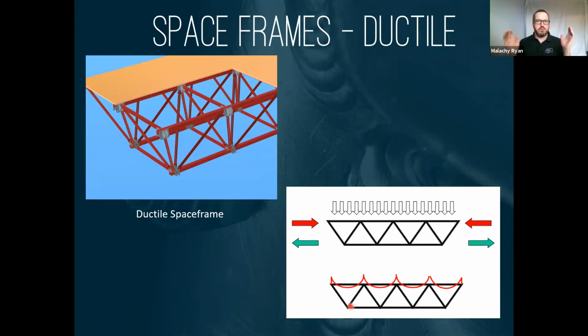Because you've lifted that bending moment diagram on the upper side, it means that the weakest member now is the bottom, and what you have in a tension failure, it's not a sudden failure. You get notice of it. Speaking to Alan White, he's always said that it almost screams, the member screams when it's getting elongated and pulled apart. We're talking about failure methods here, but you need to know these failure methods in detail so you can look at redundancy, and that's something we're going to discuss in detail in a while.